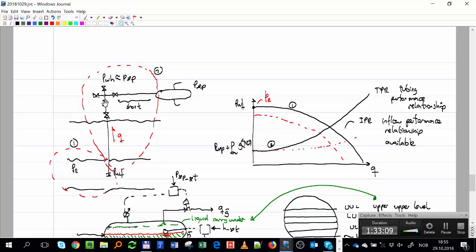And then I calculate, if I have no flow, let's say everything is filled with gas all the way down. And I have here just separator pressure plus the column of gas. So that's this point here that I call density average times g times TVD, which stands for true vertical depth of the reservoir. TVD is also another term that the drillers like to use a lot.